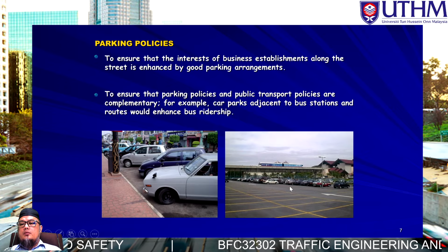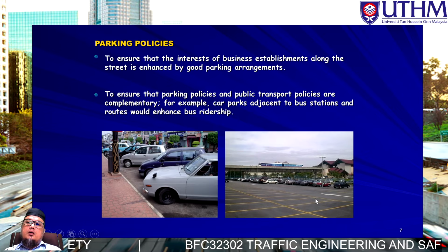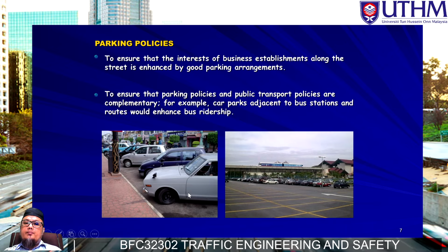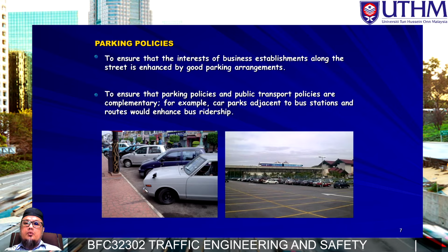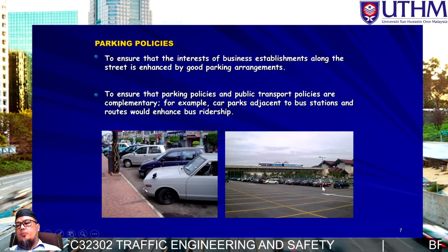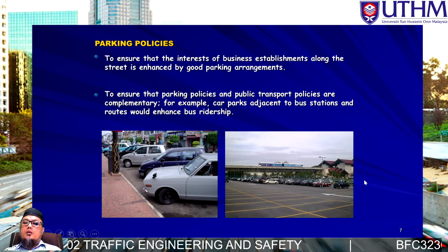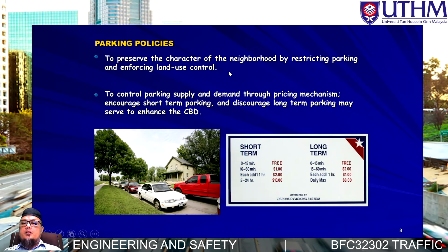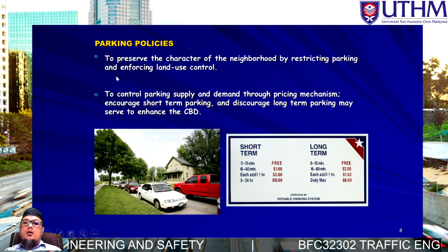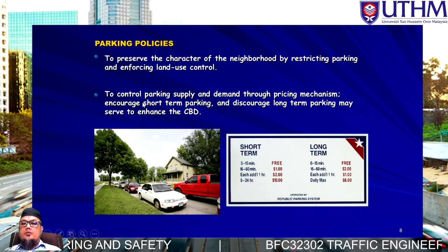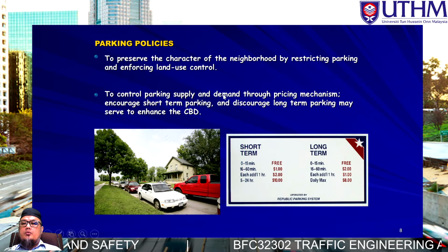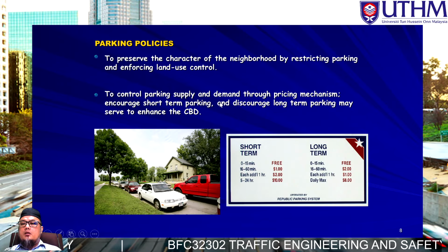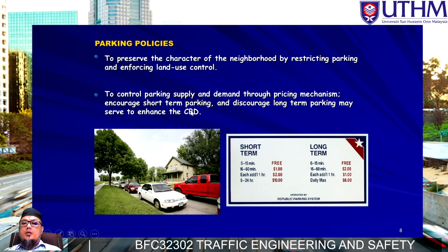So we just give some alternative to the road user or motorist, instead of them using their private vehicle to go anywhere, they just park in one place and take another alternative mode of transport. Okay, to preserve the character of the neighborhood by restricting parking and enforcing land use controls, to control parking supply and demand through a pricing mechanism, encourage short-term parking and discourage long-term parking to enhance the CBD.